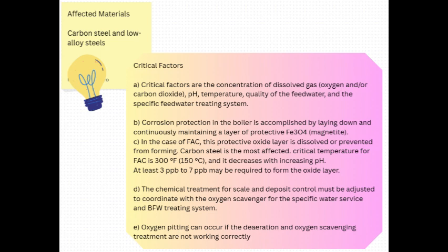And what conditions make this FAC process really take off? Are there specific temperatures or water chemistry factors? Yes, the sources are very clear on this. There's a peak danger zone for temperature. The single most critical temperature for FAC is 300 degrees Fahrenheit. That's 150 Celsius. 300 F. Wow, very specific. If your water's flowing fast in that temperature zone, you're at maximum risk for FAC.